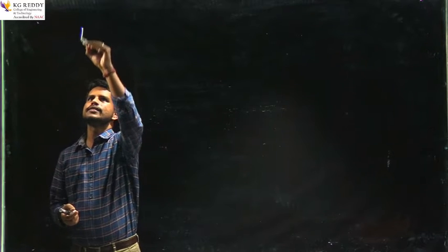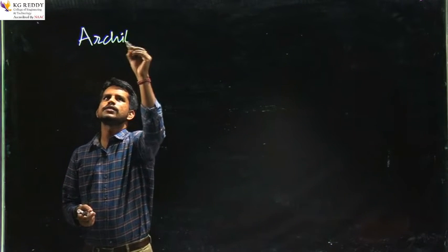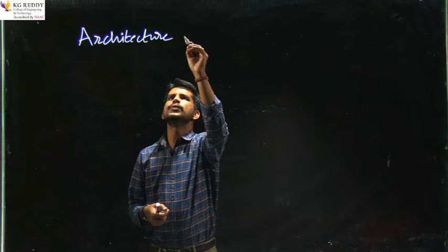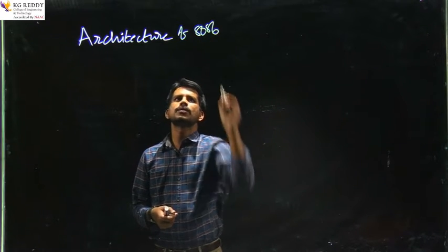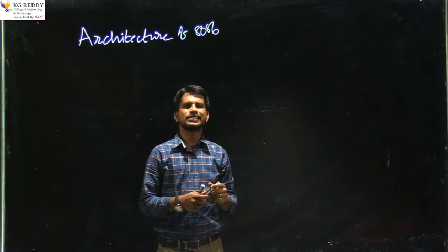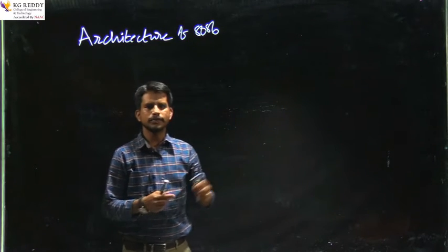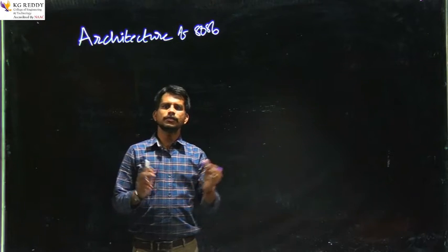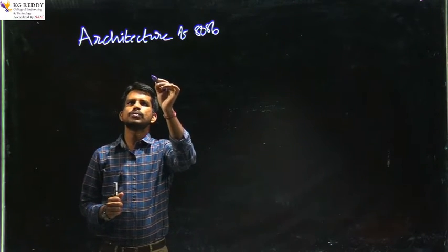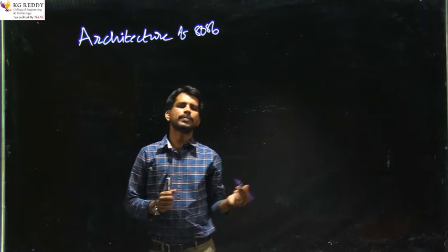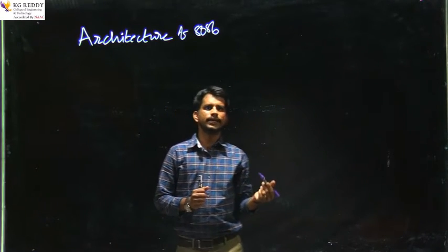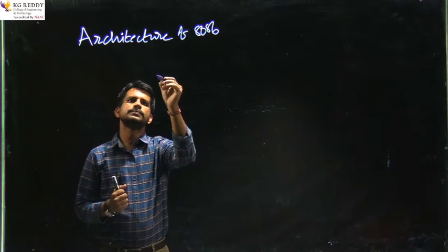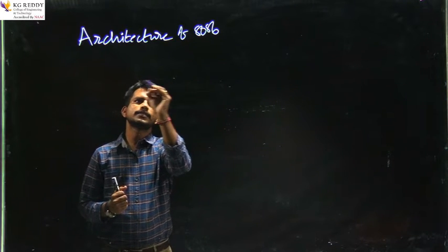Okay, 8086 is a 16-bit microprocessor, where it consists of a 16-bit ALU and performs all the arithmetical or logical operations of 16-bit size. Okay, and we are going to discuss the internal block diagram, nothing but the architecture of 8086 microprocessor. Basically, the architecture of 8086 is divided into two subparts based on the pipelining operation of the 8086 microprocessor. The first stage is called the bus interface unit, and basically it consists of